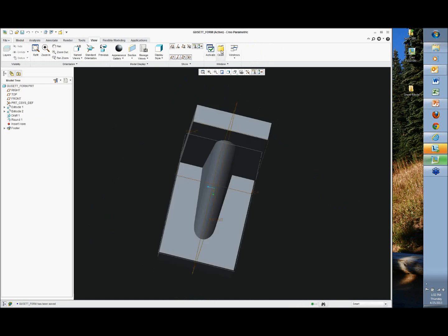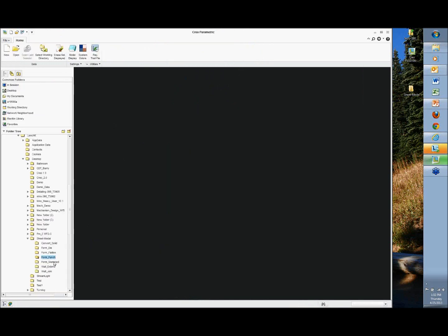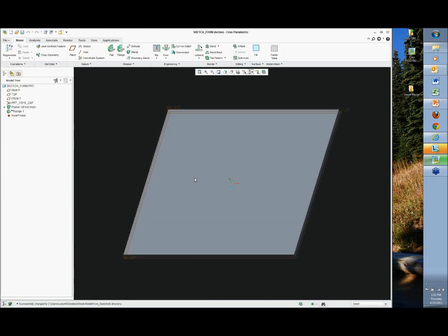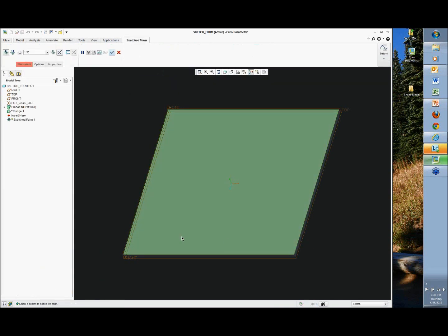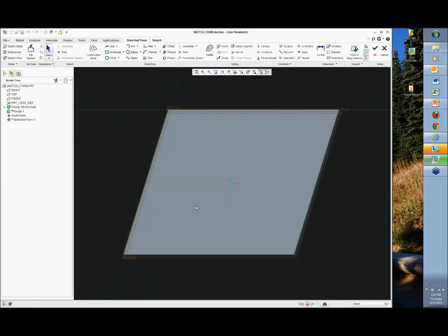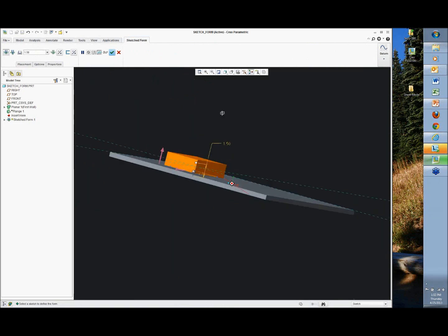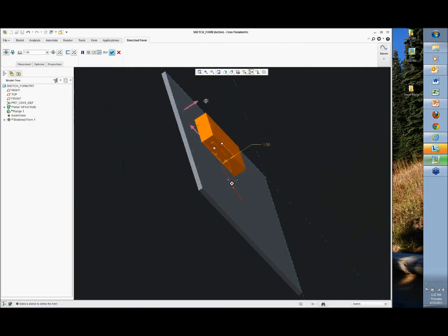Then the brand new punch tool is called Sketch. So now, instead of carrying all those parts in the library and all that kind of stuff, this brand new tool allows you to go in here and just build a sketch form, pick a surface to sketch on, grab a shape, whether it be a rectangle, whether it be a circle, whatever it is, and you can see automatically I get some kind of shape punched through there.